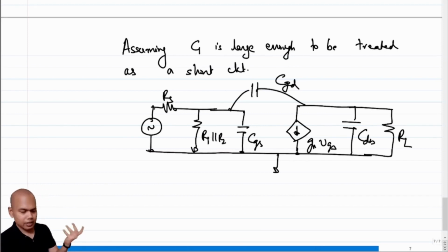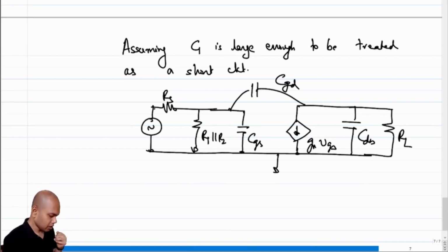We have neglected channel length modulation because we have RL, so we can neglect channel modulation. Okay, so if this is the case, then we have to go ahead and analyze this structure once, before we understand what is the impact of adding these capacitances and how it affects our life going forward. So that is what we will do next.